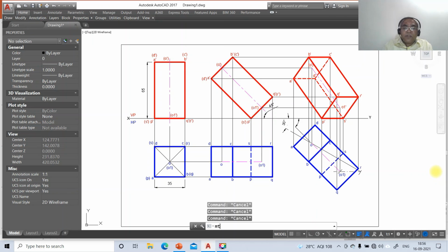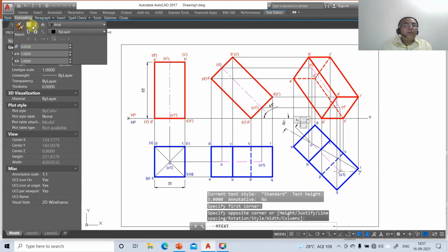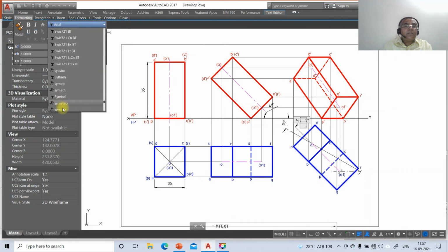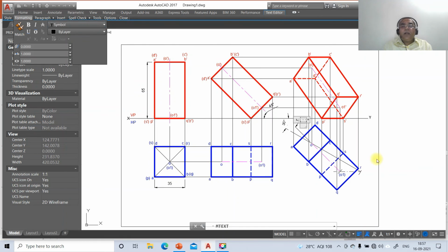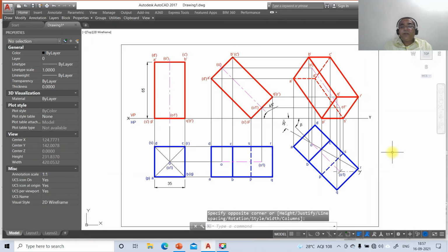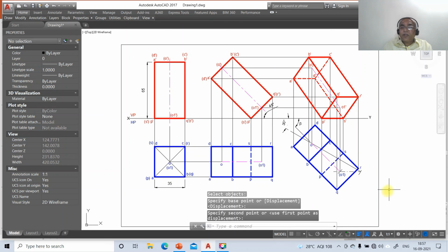This is how we'll be able to draw this drawing by using AutoCAD. So now we have the last one which I need to represent, which is beta. So you just go to that, then go to formatting, go to symbol, select this symbol and type small letter B, which gives you beta. So this is your final drawing by using AutoCAD. Thank you.